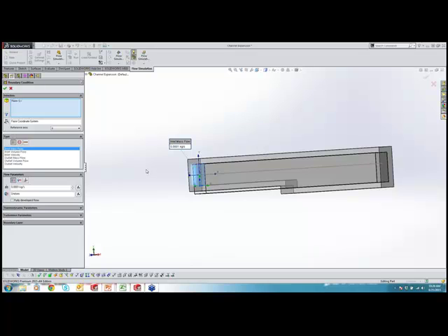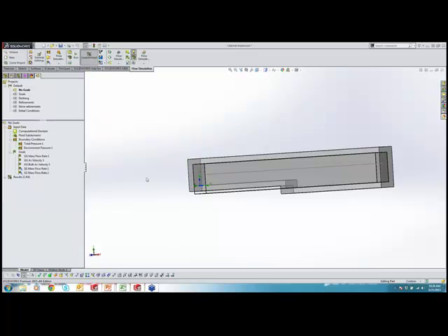It has to be something that's a rotating mesh in order to capture a moving mesh. Okay. But you might be able to have a rotating mesh that, like, I know that I've seen that done for a ball valve, where they had a section that rotated, and they had the section inside rotate into position, and they had really, really tiny time steps as it rotated into position.